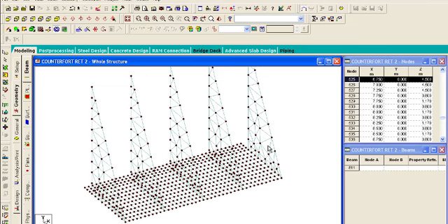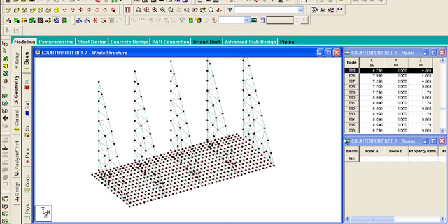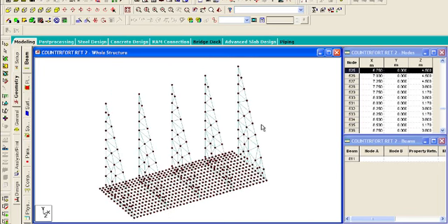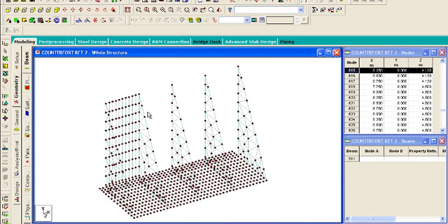Okay, we can now model the stem walls. Even though the divisions of the counterforts are looking too big, we can reduce it. Let's take this. Obviously, for this we have to maintain this same division of 10 so that the walls can intersect with the nodes of the counterforts.